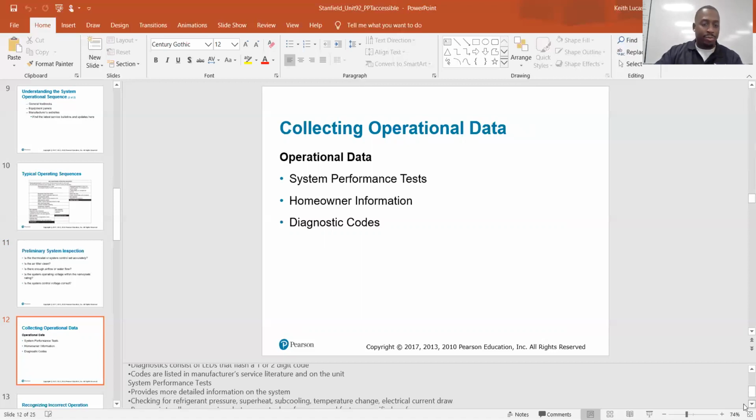So y'all real familiar with that by now. Those diagnostic codes coming up, and you check the panel. It breaks it all down on the data tag, what each code means, and you can't get totally locked into those codes because they don't tell you everything, but they're a very good guideline. And also, if the codes are making absolutely no sense, we know by trial and error it's probably a bad board. But you want to confirm that with your voltage test, which we've done.